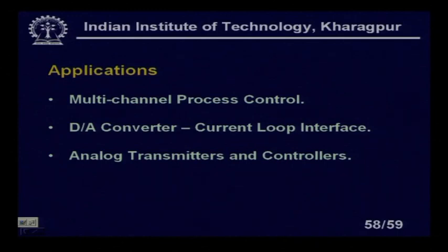I have to transmit that signal to many places, even though it is digital, but the transmitter is analog, because when it goes to the computer, it has a data acquisition system at the input. So, it will convert to the digital domain, but before that it goes from the sensor through the transmitter. So, this 1B22 will be incorporated within the transmitter. That means it will convert, suppose for pH, whatever the voltage I get, to a current of 4 to 20 milliampere, that can be achieved there.